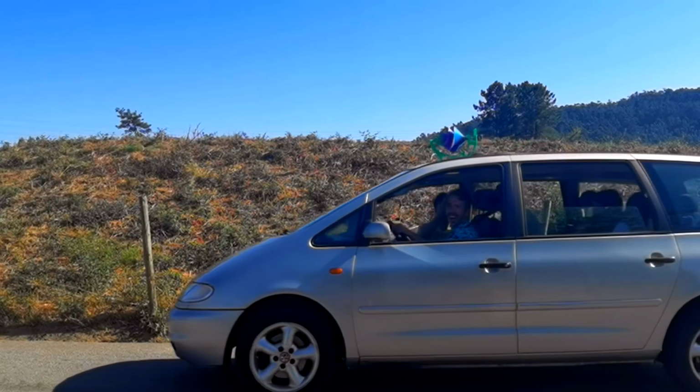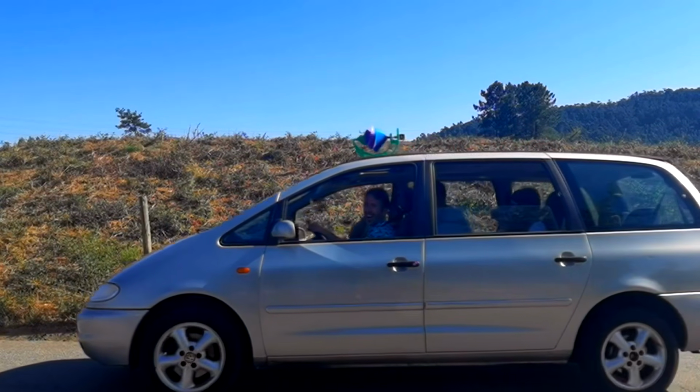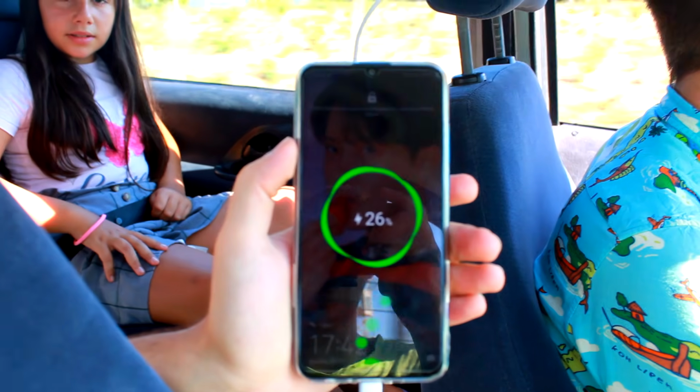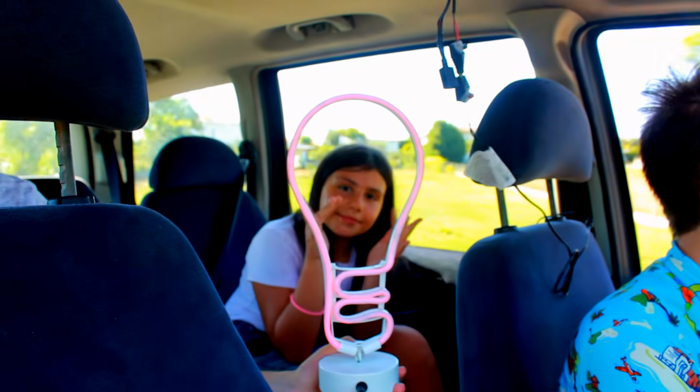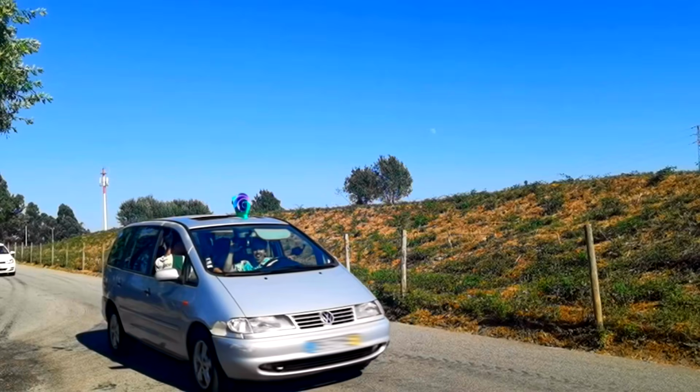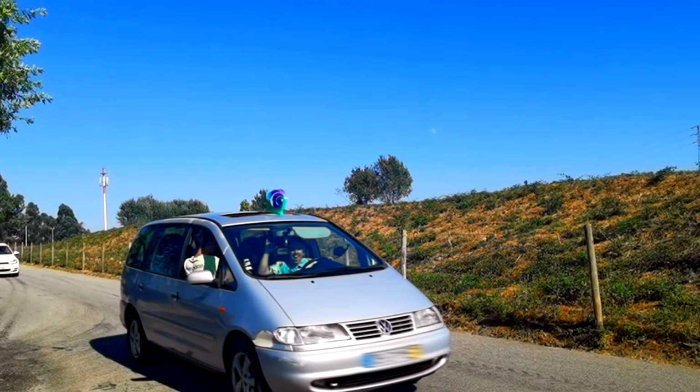30 km/h is a good test speed because it's not at all uncommon in nature. At this speed, the turbine could easily charge my sister's phone and light up the red light at the same time. I actually found out that for low loads and wind speeds of about 30 km/h, the turbine is able to output as much as 8 watts. If I use it to charge batteries using natural wind, I might get a decent amount of energy out of it. But for now I need to wait for natural wind.